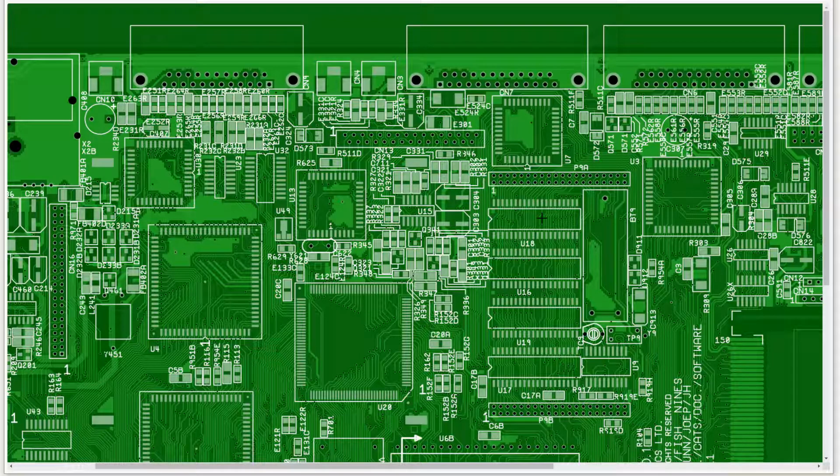This is important to me because the less time I spend with my oscilloscope probe poking around in here with the system powered up, the lower the odds I'm going to have the probe slip. I could have the probe slip from the plus 12 rail here and create a bridge over to this pin here. And if I drop 12 volts on that pin, there's a chance I'm going to damage something.